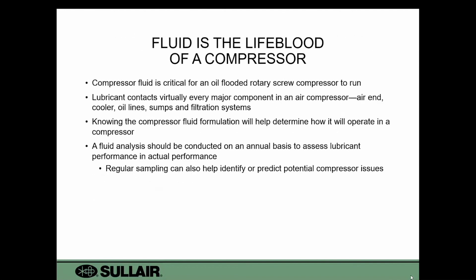So one thing to remember is that the compressor fluid is the lifeblood of your air compressor. It's not just putting oil in your machine. That's not the way you want to look at it. The condition of your fluid is very important. The type of fluid that you put in is very important. And continuously sampling it lets you chart out and determine where the performance is so you can lead to the longer life of your air end.